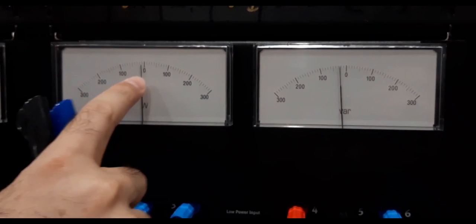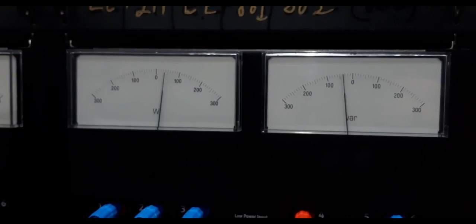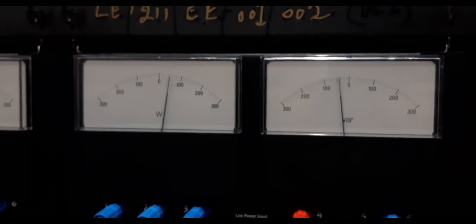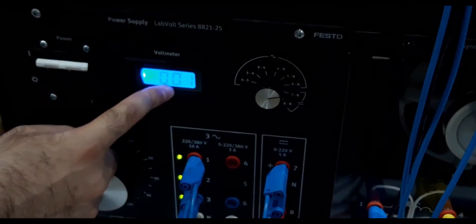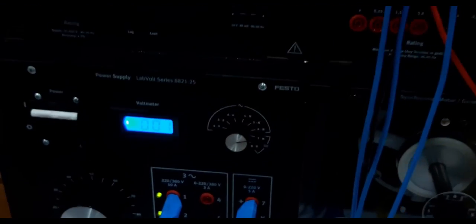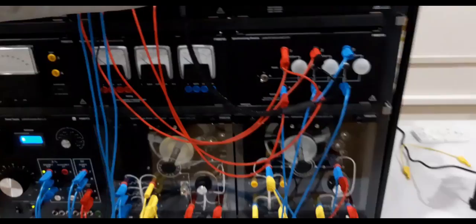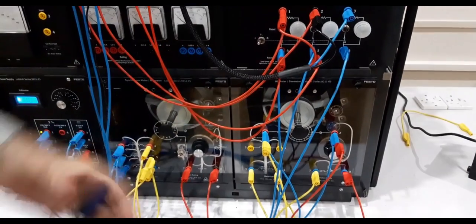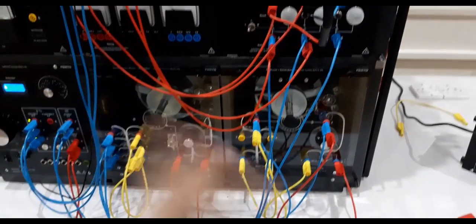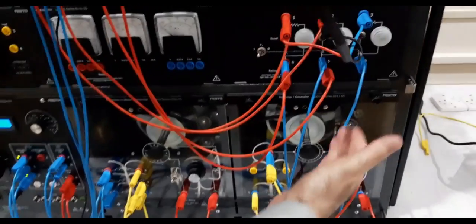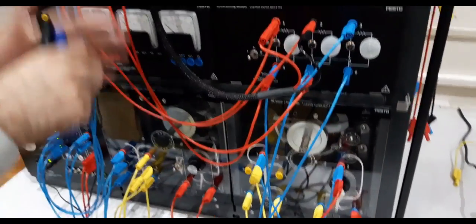Now even the active power has moved in the other direction. You see, the prime mover voltage is 0, which means that the prime mover power is 0. But since this system is connected to the grid, the connection is still there. Even though the prime mover power has been reduced to 0, since this connection is there, what will happen? The system will provide active power because the machine is a slave of the system.